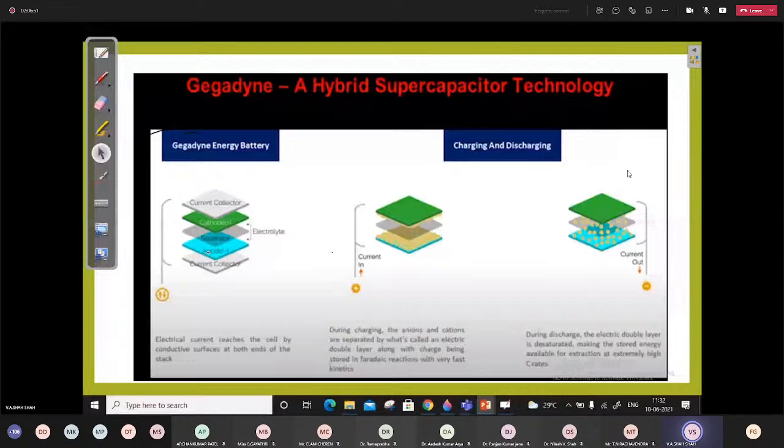And this is the simulation that has been performed with this drive cycle: acceleration, constant speed, deceleration, again acceleration, and constant speed. In this case, you can see that during acceleration, the torque will be positive. At constant speed, it requires a smaller amount of torque.